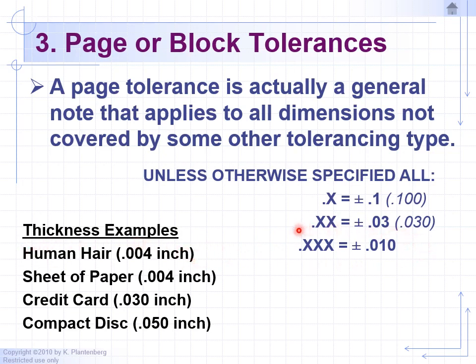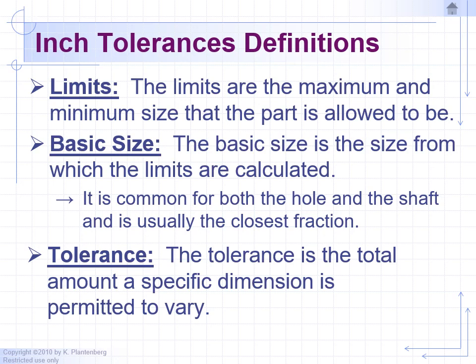Okay, so this is very common to see on a hole that needs accuracy. 2 decimal places is the most common that you'll see on a drawing. 1 decimal place, not very common. It's something that you'll see on large objects where the length is not that important. And you can tell them they can be off by 0.1 inches in either direction.